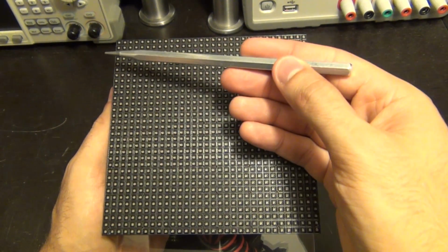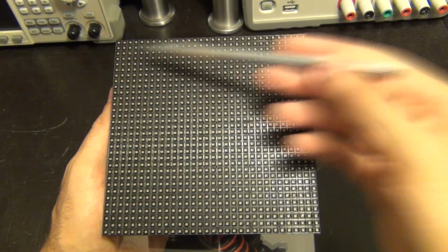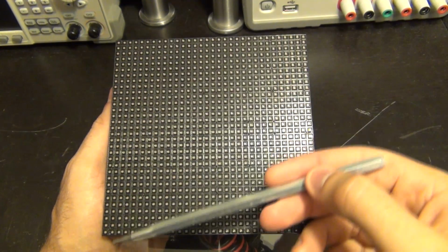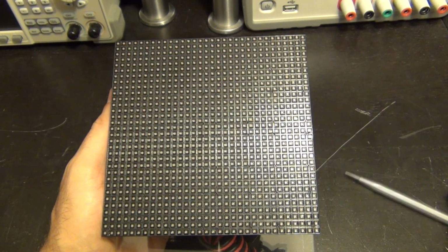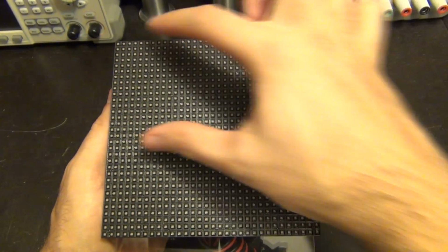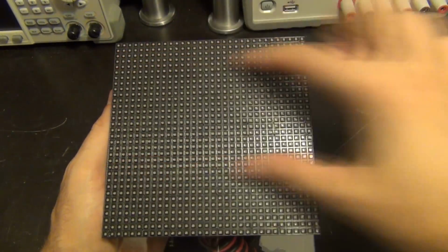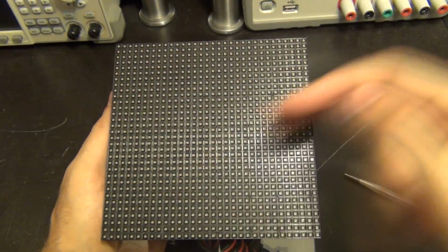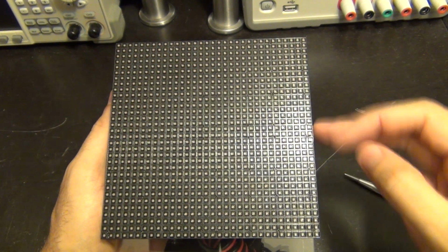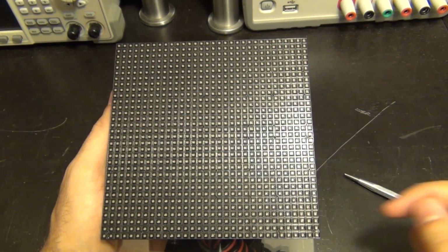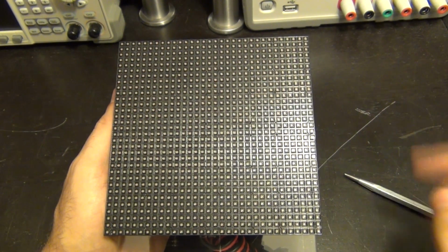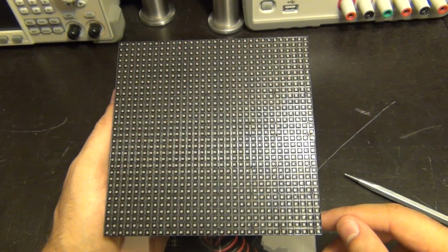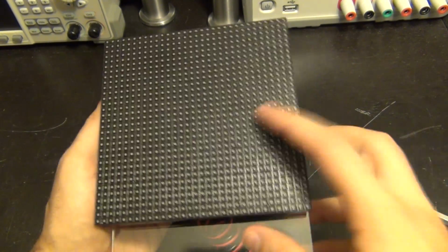Now another thing they do is that they have a 4-bit address, and because they have a 4-bit address, well, obviously 4-bit doesn't cover 32 rows, it can only cover 16. So this display supports writing to 2 lines at a time. So you write these 2 lines and then you move to the next one, and then you move on to the next one, and all the way down by 16 you have written an entire frame. So you fill this and this half simultaneously. They do that so that you can achieve higher frame rate by essentially having to write only 16 rows as opposed to 32.